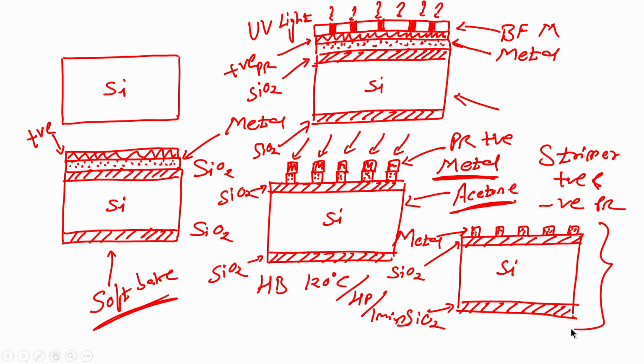I will have a substrate which is an oxidized silicon wafer with patterned metal. Now, before I dip this wafer in metal etchant, I can always do the inspection of the photoresist patterning. So, this is a photolithography technique. I have given one example where you can create interdigital electrodes with the help of photolithography.